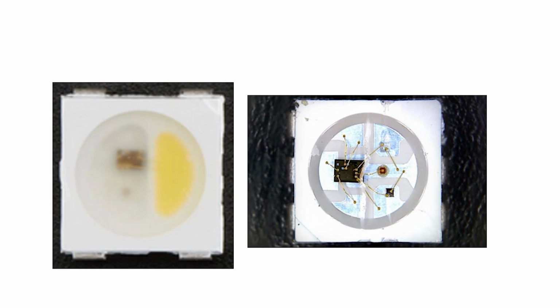And another thing to notice that not everybody notices is that in the top right of the left-hand image, there's a wee corner chipped off, a little bezel on the corner of the NeoPixel. This thing's square. There's 4 ways you can put it down, and there's certainly 2 ways that you can put it down with the connections. So you have to get it the right way around. And that's what that wee triangular chip off the corner's for, so that you can orient it the right way around. And if you look at the other one, the little chip is in the bottom left for orienting it the right way around.